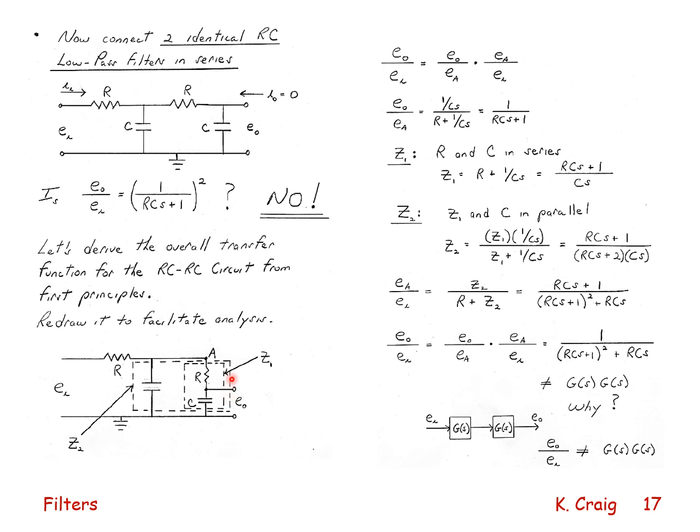Now, I can look at R and C and say they're both in series. Impedances in series add. So Z1 is what I have enclosed here in the dashed box, and it's the sum of R and C in series, which I simplify here. Then I recognize that Z1 and this C are in parallel, and for impedances in parallel, the equivalent impedance is given by the product over the sum. That's only true for two impedances in parallel. And if I simplify that, I get this relationship.